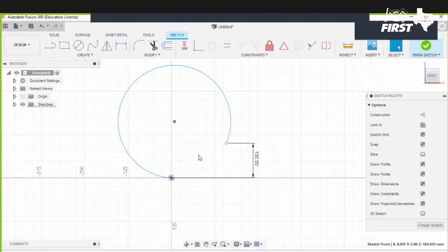So like I said, what just happened right now is I already had the center of that arc picked. And when I made my dimension, I already had that 1 point specified. So by the time I made this line, it was already off. Because what I want to have happen is compare this line, this point, with this point of the origin. So make sure that you always have things unclicked before you make your dimension, or at least be prepared and understand that you might have already clicked something.